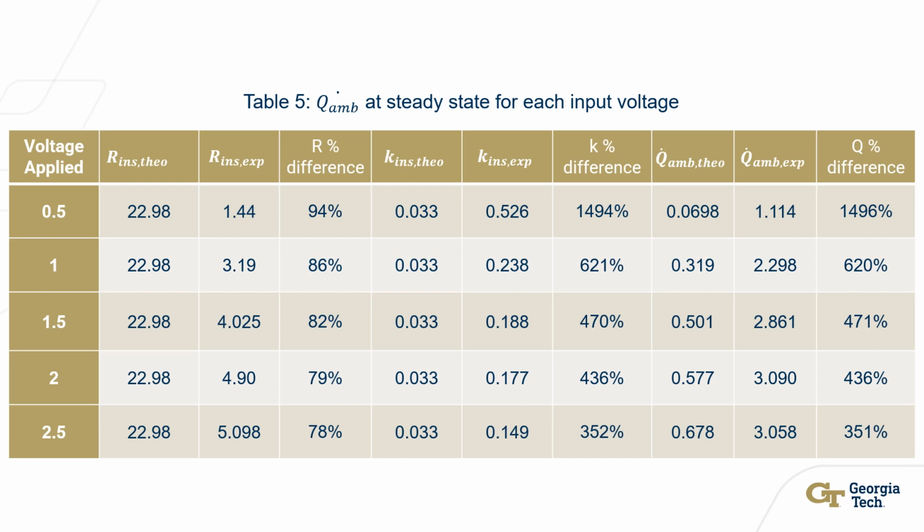This can be attributed to assumptions made in the model that are not accurate. The styrofoam block that was used was taped together with gaps along the seams, leading to losses in energy. In addition, the thermocouples used to measure temperatures, especially the one for load, were not placed in the center of the load as assumed by the model. They were placed on the edge, leading to lower temperature values. This led to a higher amount of energy lost, as seen in the higher values for experimental.